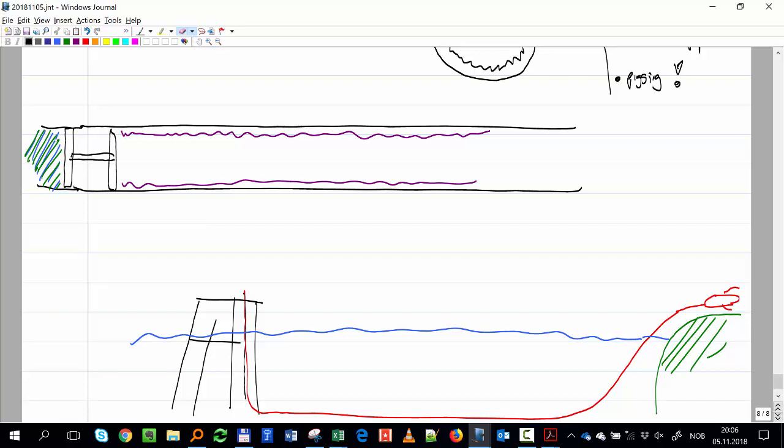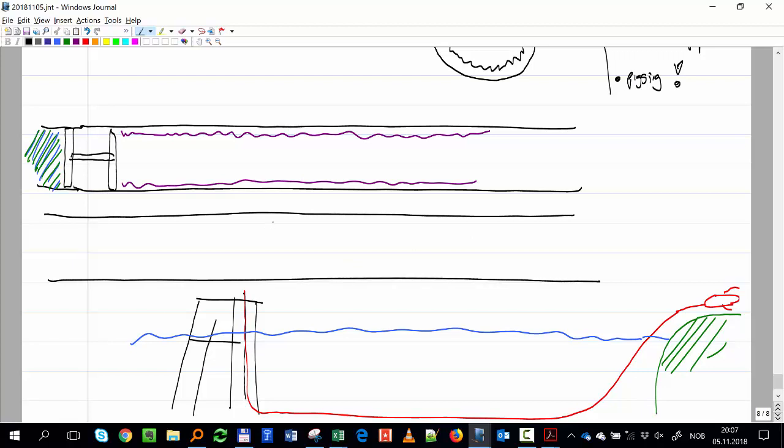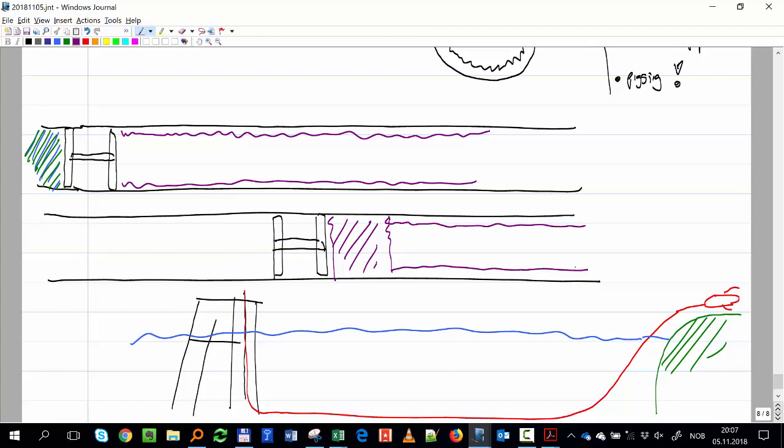Okay, let's say that the peak moved to another position in the pipe. Let's say you have it here now. It will now have just a block of wax in front, and it will be scraping here now. Behind you have the oil. If that block becomes too big, then you cannot push it. You're going to be stuck someplace in the pipe.